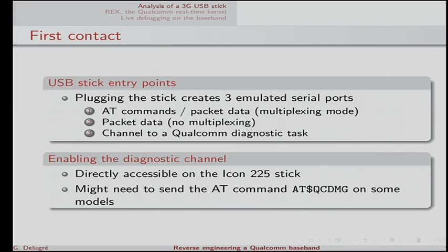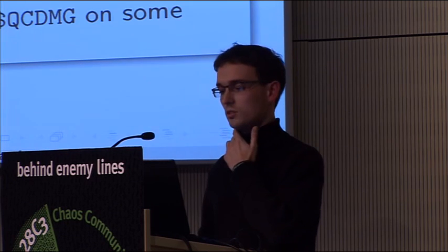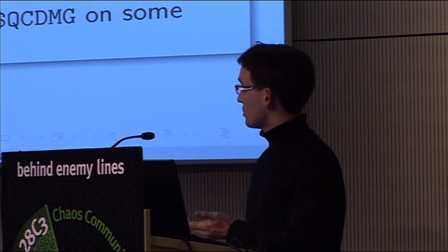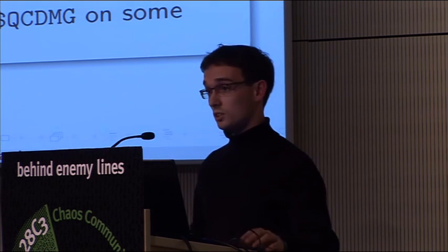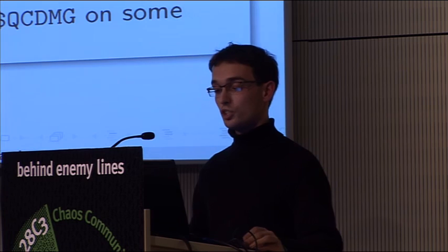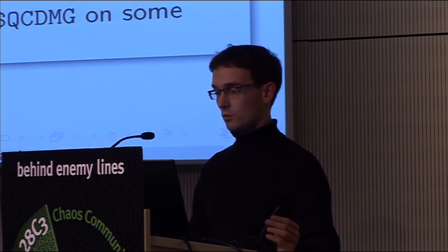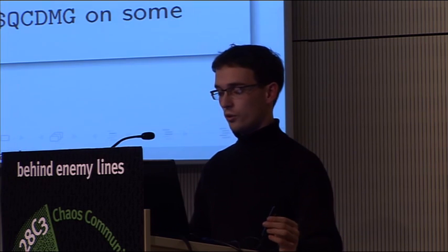If you plug this USB stick into your computer, you will see, in fact, 3 serial ports firing up. The first one is used to pass AT commands to the modem, and also packet data if the serial port is multiplexed. The second port is only used for packet data when the ports are not multiplexed. And the third port, which is interesting, is a channel to a Qualcomm diagnostic task, which is something left by Qualcomm engineers to debug the baseband.